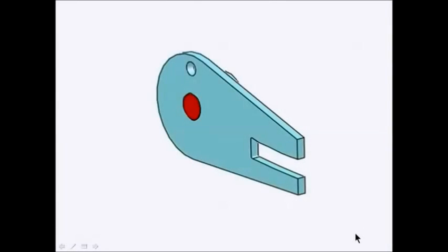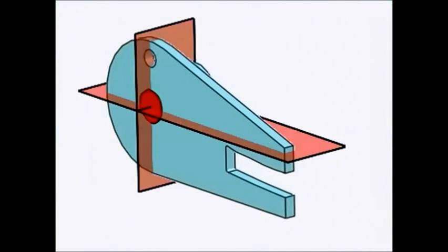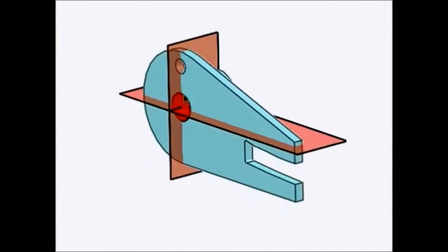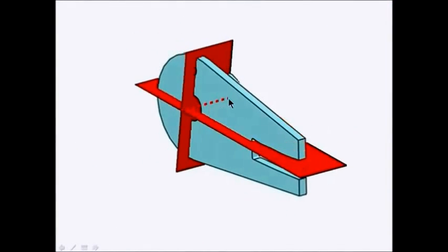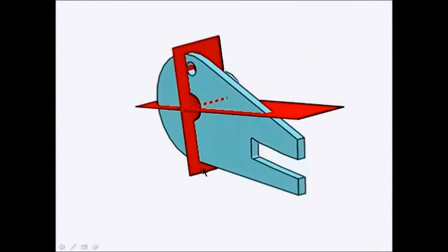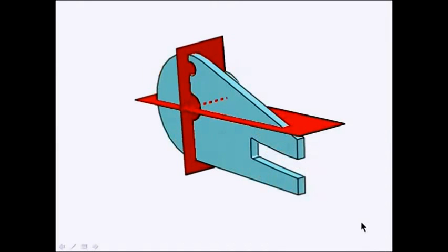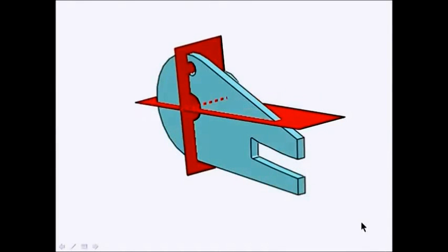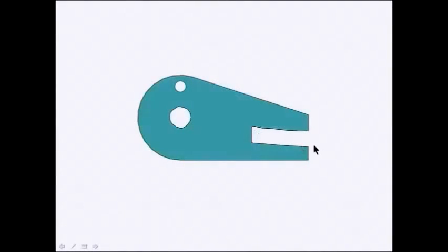As I mentioned, first you would fill datum feature A with the largest inscribed cylinder. This gives you an axis. The axis is the intersection of two mutually perpendicular planes. The question is, how do I now orient these datum planes? Well, the slot was picked as a secondary datum feature. There's two ways that I can use this to orient the planes.